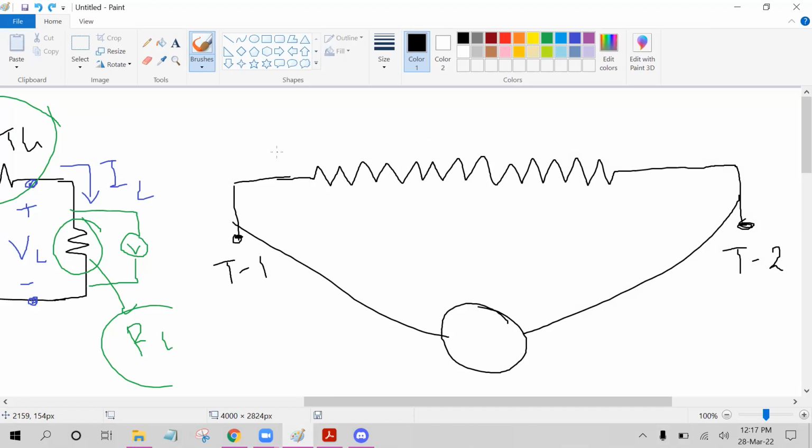For example, a potentiometer can be 5 kilo ohm, 10 kilo ohm, 100 kilo ohm, etc. That rating means that this is the maximum resistance of the meter, which is situated between terminal 1 and terminal 2. So for this particular potentiometer, if we measure the resistance, we will get 5 kilo ohm. Is it clear?